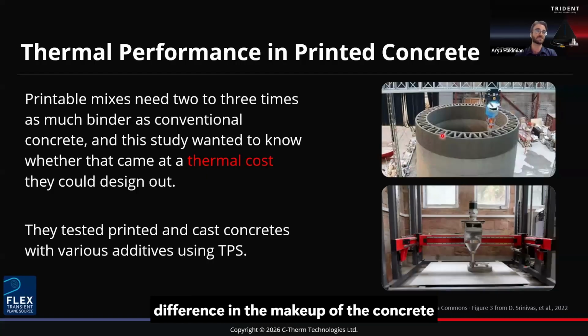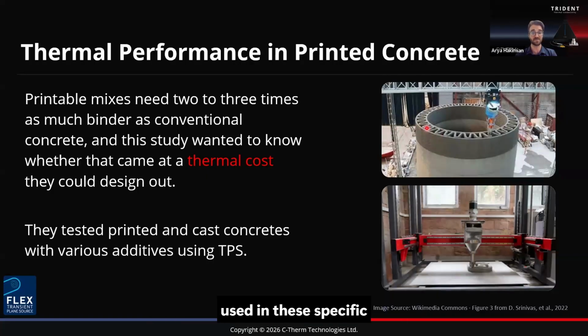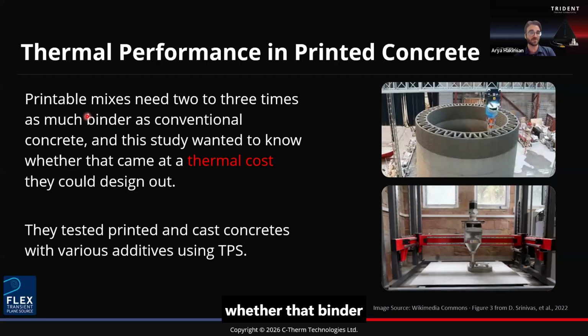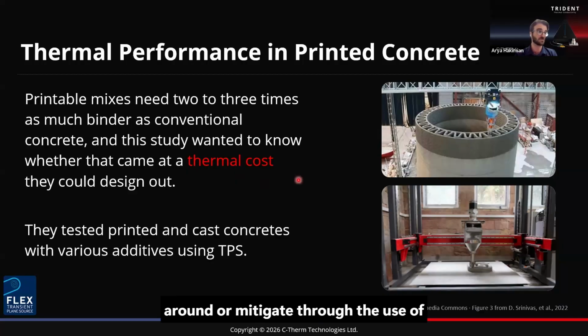But there's a difference in the makeup of the concrete used in these specific applications, specifically that these mixes need significantly more binder compared to conventional concretes. And in this study, they wanted to assess whether that binder difference came at a thermal cost that they could somehow design around or mitigate through the use of different additives and fillers.